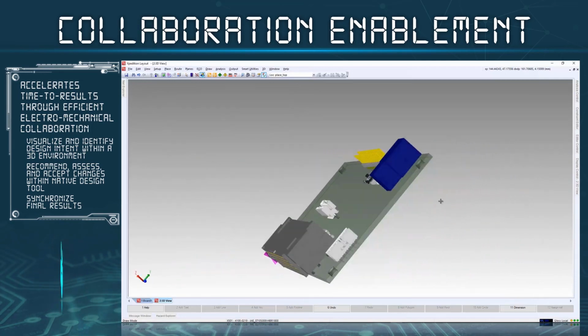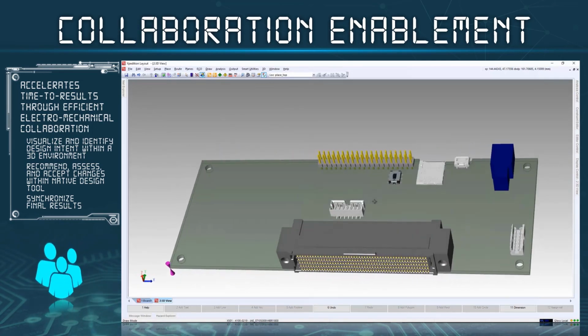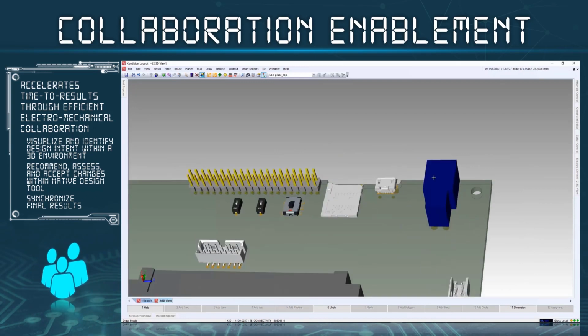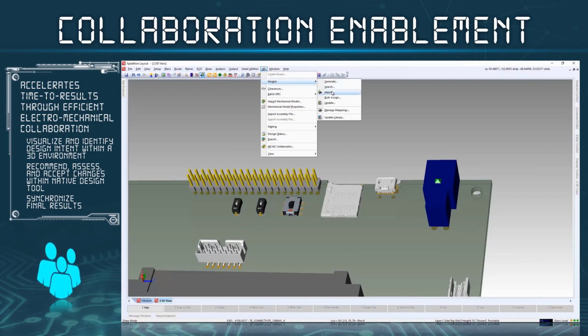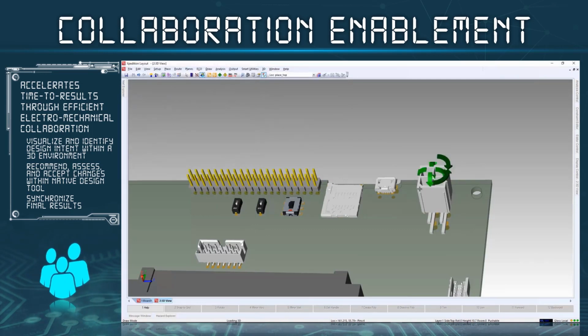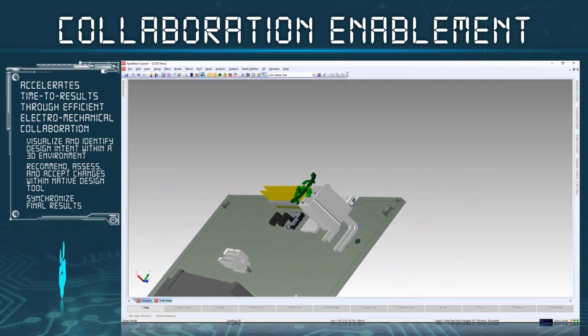Notice that one of our components is using the 2.5D model instead of a 3D. This is due to the fact that the component does not currently have a 3D model association. Expedition provides advanced model alignment capabilities to make this process painless. After you've found a model available publicly or created one yourself, we'll import the model into the design.